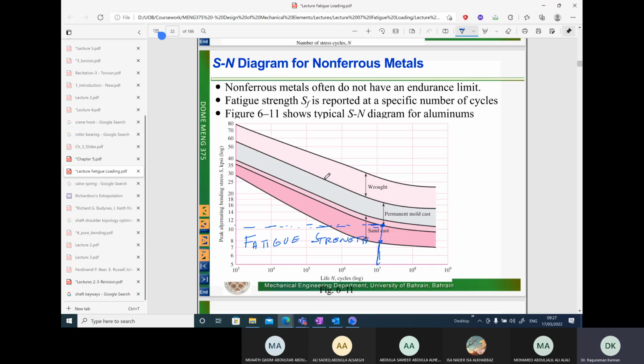Open ANSYS, and you will see material properties for different kinds of material, including steel, aluminum alloys, copper alloys, etc. Different alloys can be selected, and in fact you can extract the material properties, even for fatigue, in the case of other materials from finite element packages like ANSYS and others.